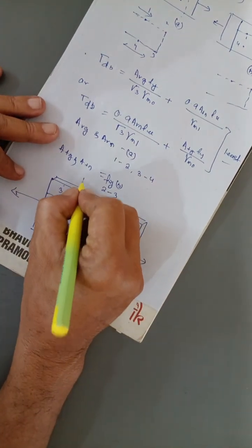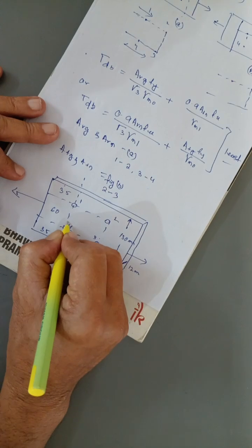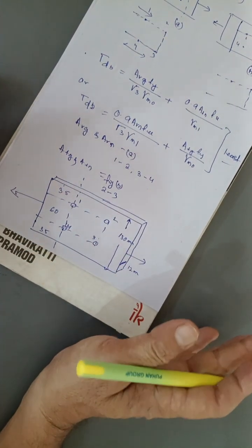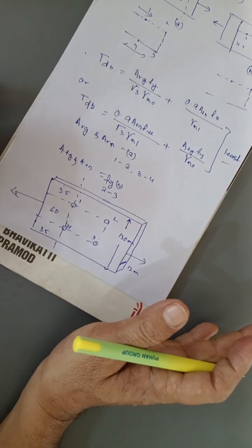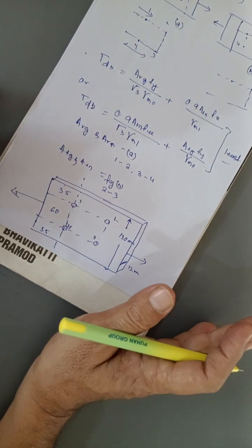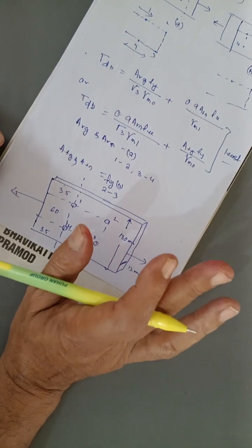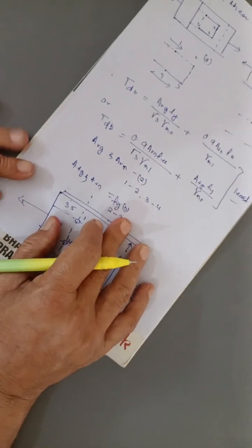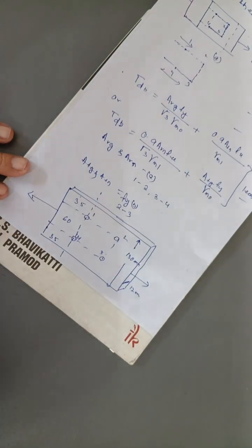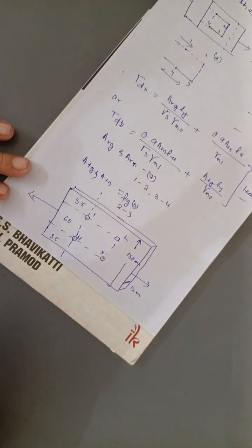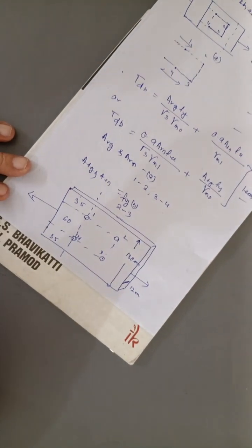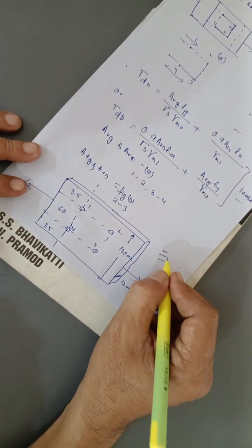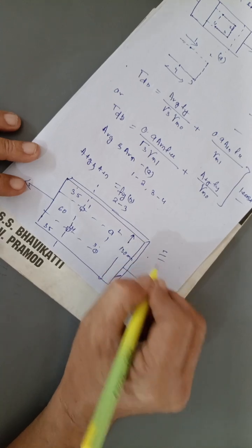Here we are considering a critical section. We are determining the design tensile strength, which we calculate from the strength of the plate. As you know, we are discussing the yielding of gross section, second the rupture of critical section, and the block shear strength. We first calculate these three values, then the least one is our actual value.